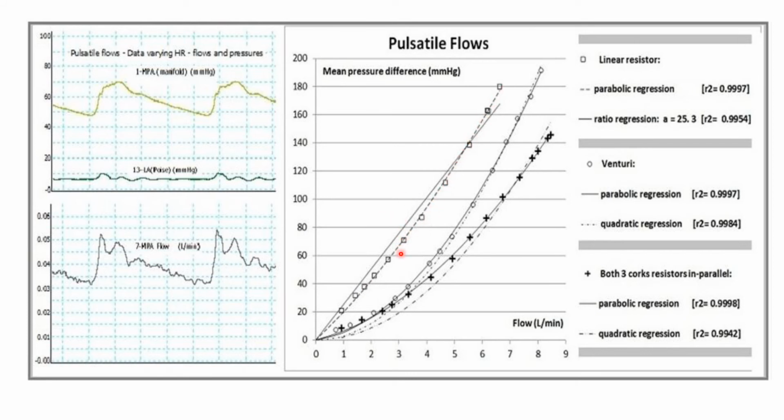What's happening here is that Darcy's law has the same behavior as Poiseuille's law, but when you force the flow very much, you start having kinetic energy inside the flow, despite it being a foam. And then you have to use the Forchheimer equation. And the Forchheimer equation is the same equation as the parabolic equation. So that's why the parabolic is fitting very well, because no matter what it is, it will fit.